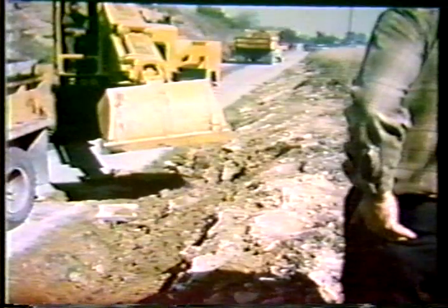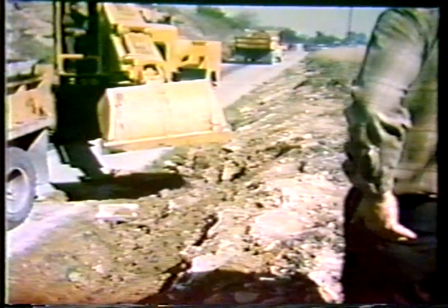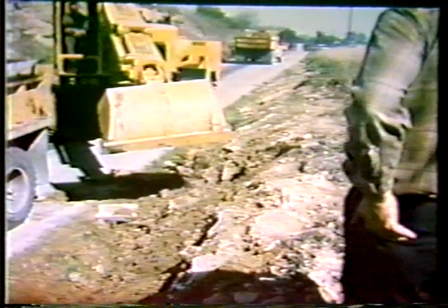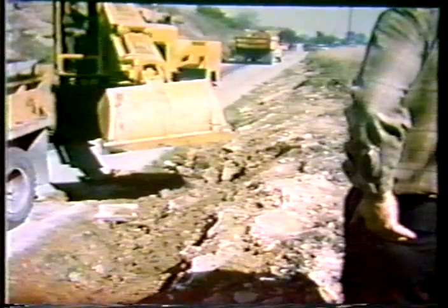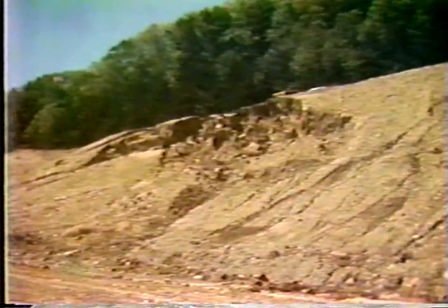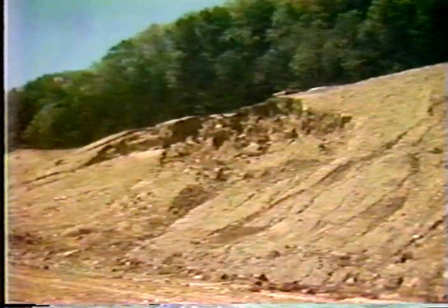And that's in a cut slope there where they're flattening, and they can solve a good problem there by flattening it back. I think originally they were getting sloughs in the cut slope material there. Another example where another type of slide where a cut slope, a slope flattening might work, is shown here.